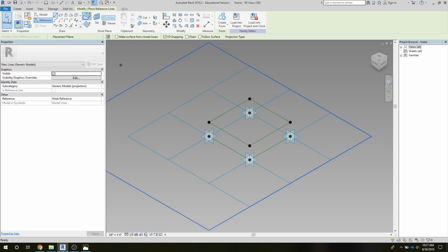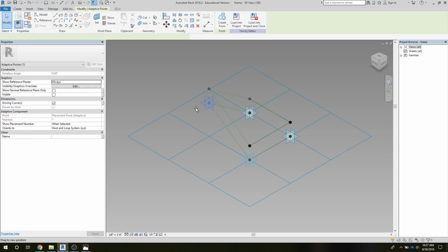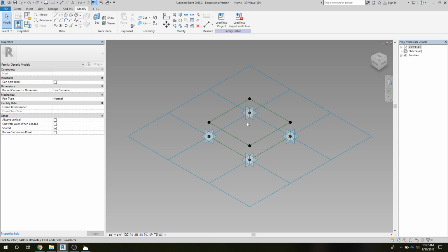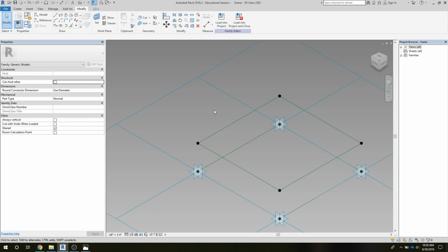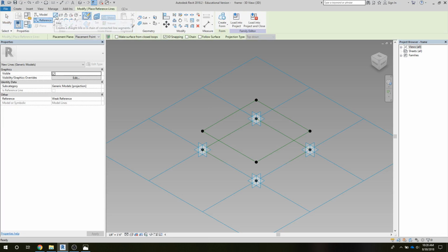And I've created now some reference lines that are up higher, and you'll notice that if I move these, the reference lines will move with them, so they're behaving adaptively. So I'll undo that. And we're going to go ahead and make a tubular extrusion around that assembly. Actually, I'm going to put in a couple more lines just so we have some indications for other things we want to construct. So I'm going to make a few more reference lines.